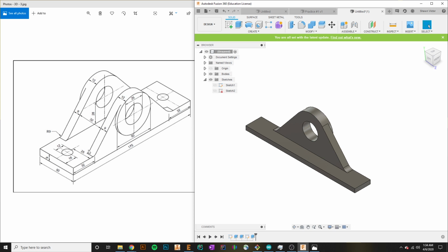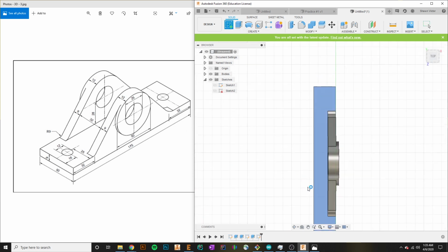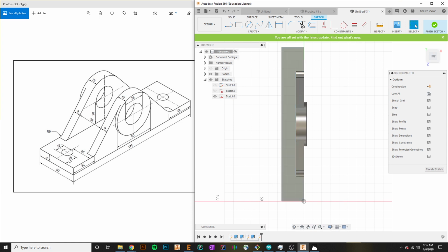Now we just need to make these 2 holes, and then we will have 1/2 of what we need. Okay, so you can see from this edge to here, this is also 25 millimeters outwards. So I'm going to use a construction line from here to here. I'm going to say 25.